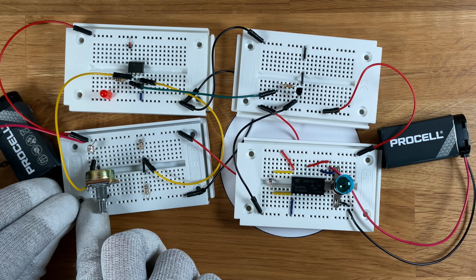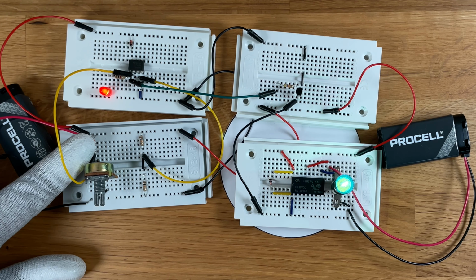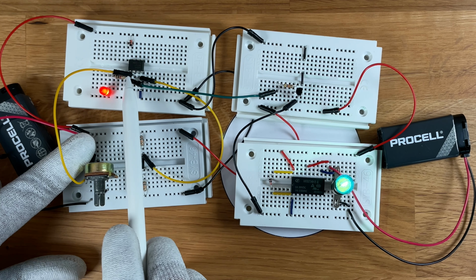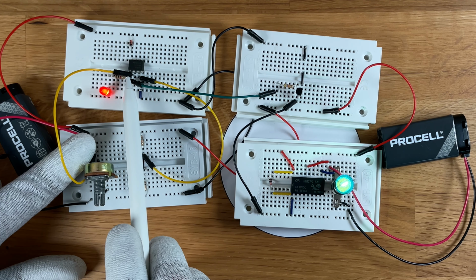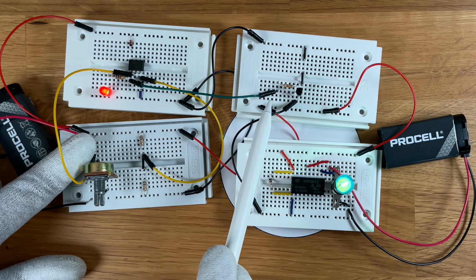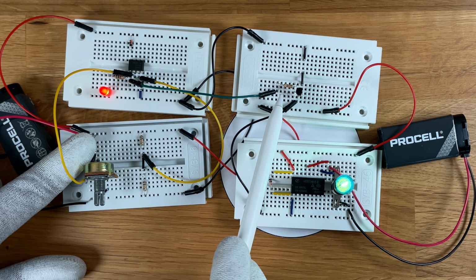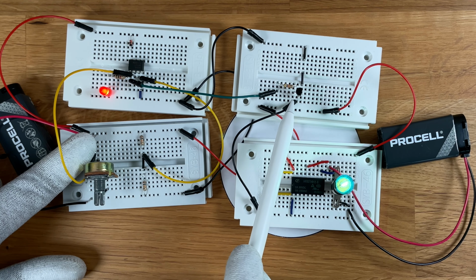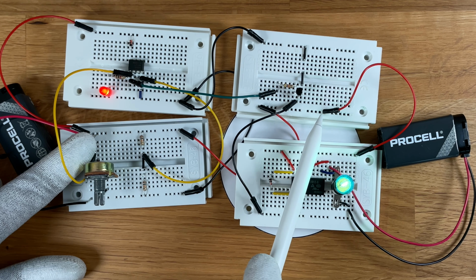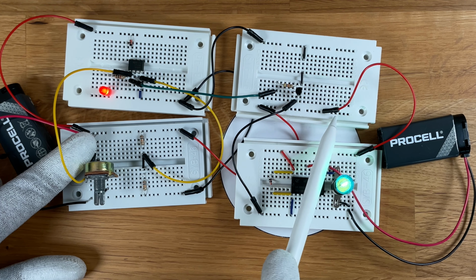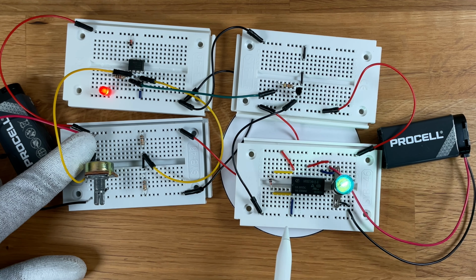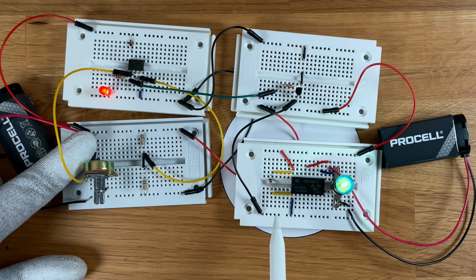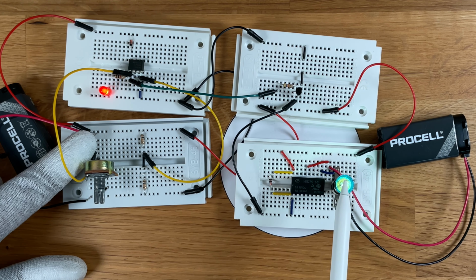Now everything is powered, and we can put our finger across the light-dependent resistor, and you can see that the LED switches on, which means the output of the comparator of the operational amplifier goes to high. This signal is transferred to the base of the transistor. The transistor starts to conduct between collector and emitter, and this current, which is running from the positive power rail through the relay circuit and back to the transistor, is what drives the relay switch, which then in turn connects the second battery to the incandescent lamp.